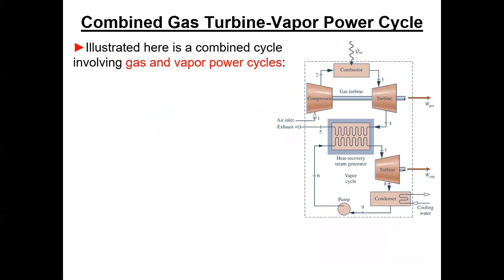So there's our first combined cycle. That's about as simple as you can draw one. Okay. So we've got the Brayton cycle up on top, just compressor, combustor, turbine, putting out a whole boatload of energy at 4. So this is going to be the heat input to our boiler, which is called a heat recovery steam generator.